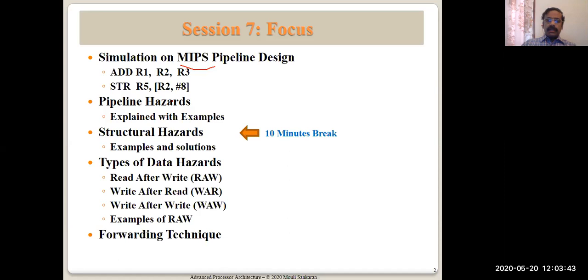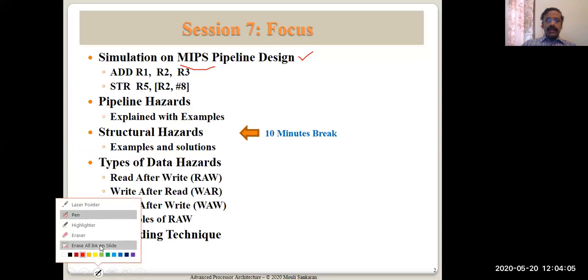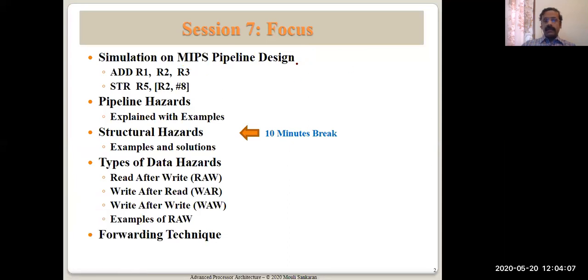The pipeline structure, how does it look inside a MIPS? What I'm going to show you is the simplest design, and the actual design will be much more complex. Then we will add a little bit of complexity to the design as we proceed. Today we will cover a couple of things. One is studying the pipeline design and then running two instructions through the pipeline. Then I will talk about a new topic, which is pipeline hazards. So let me start.